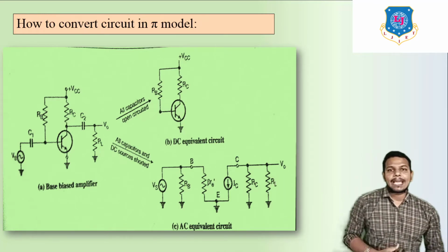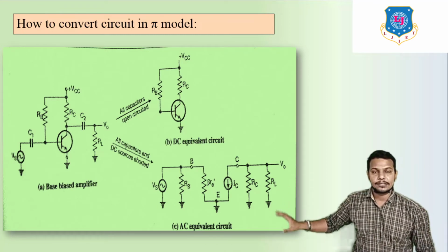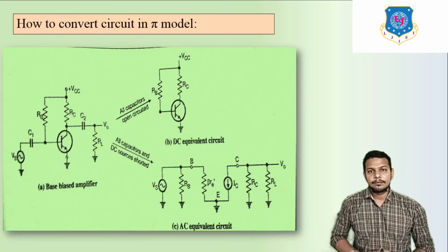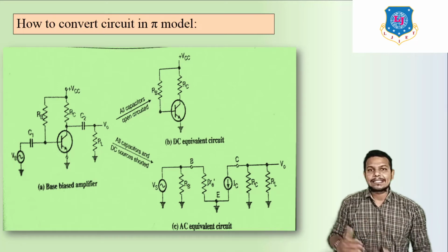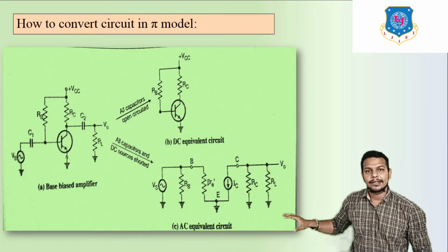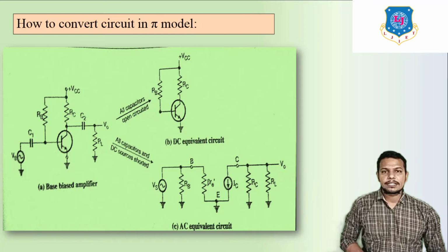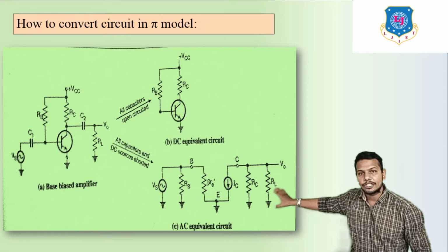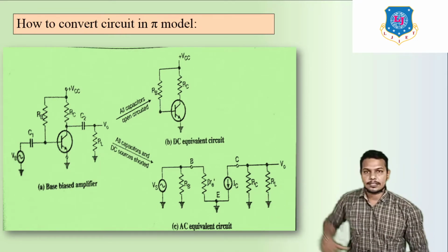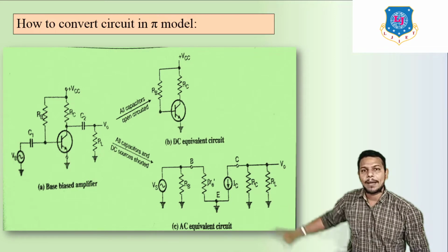Now there is one capacitor which becomes short circuited because here we are going to use AC analysis. So always remember this thing: a capacitor blocks DC signal and allows AC signal. So this is the AC analysis circuit, that's why it becomes short circuited. Now remember there is an RB. RB is connected here, which is exactly parallel to the Vs, right? Because there is a node which is divided into two parts.